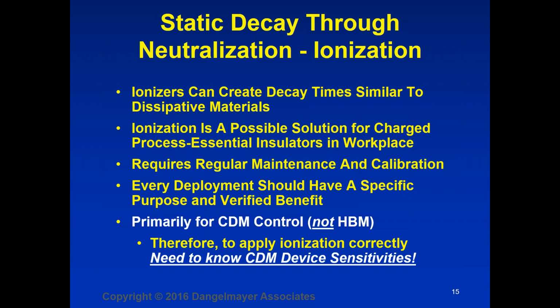I can tell you from personal experience, if you don't go after the data, you can be burned badly with class 0 devices entering the process unknown and resulting in extremely high yield losses and reliability problems. Often, not often, but we've seen 2% failure rates. So go after the data. If you haven't done it before, make sure somebody in your company is. Thank you.